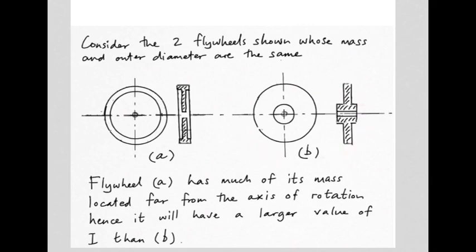And remember that a flywheel is used for storing energy. That's essentially the purpose of a flywheel. So for a given mass flywheel, you can achieve greater amounts of energy stored in this rotating object if you design it in this fashion rather than in this fashion.